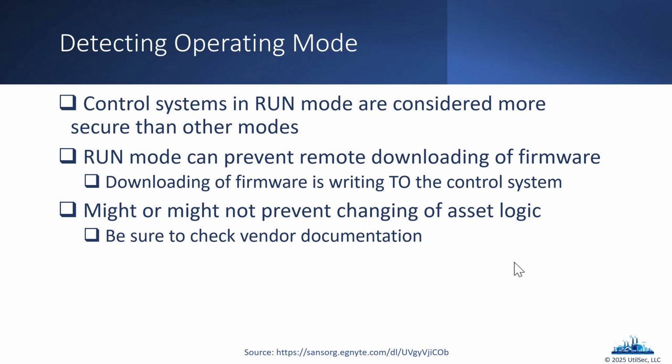Sometimes that's not always the case, but at least the ones that I had tested, and I typically try this anytime I get my hands on a new PLC. Of course, that's not in production. I want to see, can I make changes to PLC programming logic while it's in run mode? Could I potentially try to put a new version of firmware on the controller? Again, that's one I haven't found yet. But all of them have an option to allow you to change the programming language, even if it's in run mode.